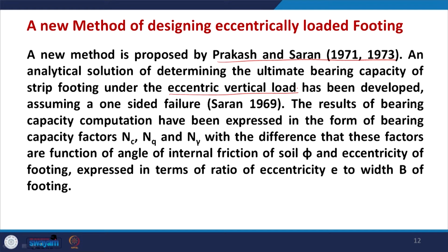This eccentricity e is expressed in dimensionless form by the ratio e/B. So, in summary, Nc, Nq and N gamma are functions of phi, which is the normal case, but they are also functions of e/B. So, let us have it here.